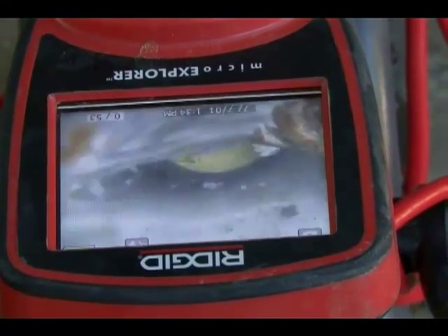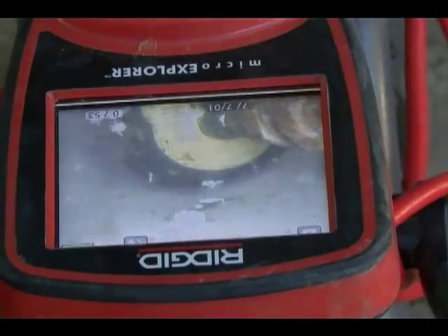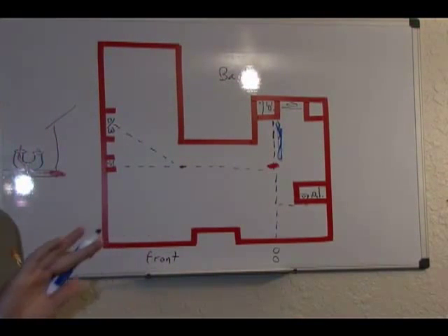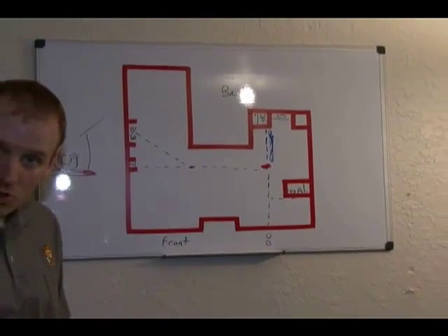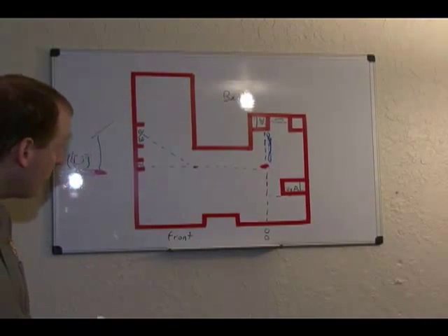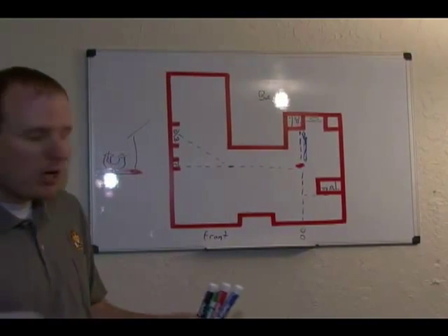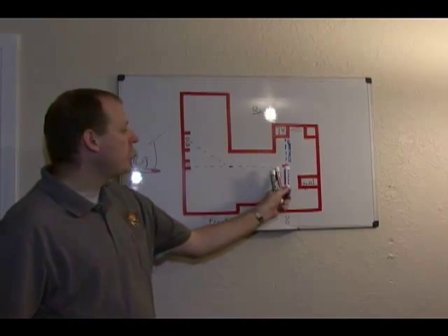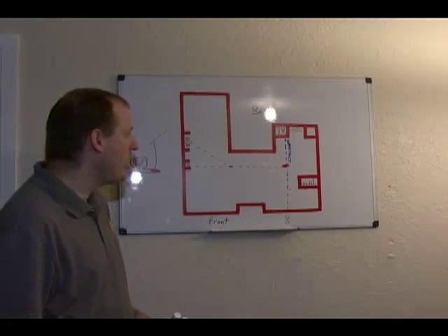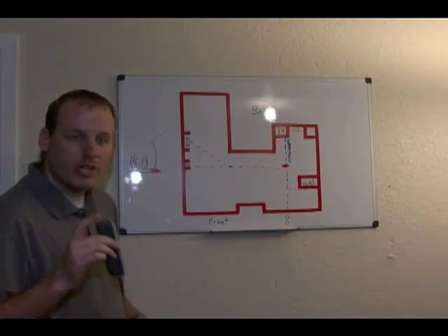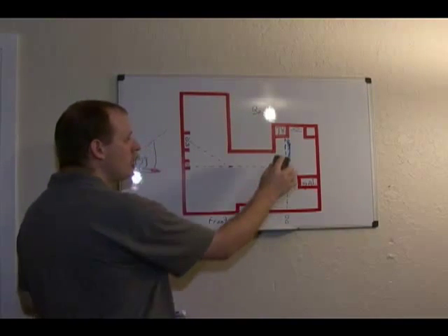Okay? We would fill it up with water. From back there. So this line would then have water in it. And for our illustration here, no leak. This section would show no leak. Okay? Now, how we actually get the test ball in there and all of that doesn't really matter for this illustration, but we can place a test ball right here in just about every case and be able to determine that there is no leak back here in this section of line.